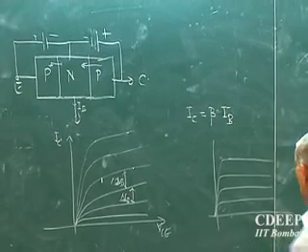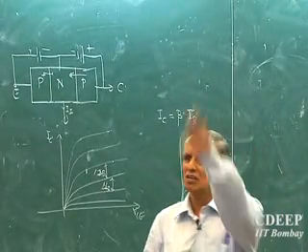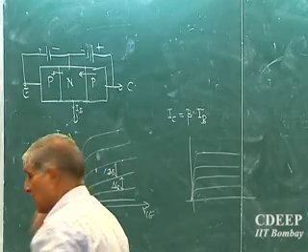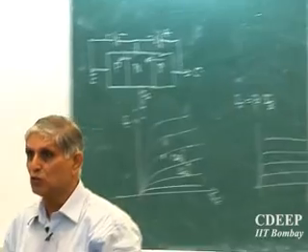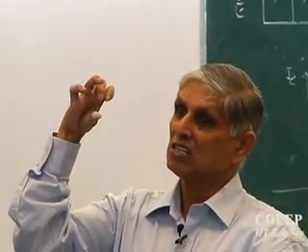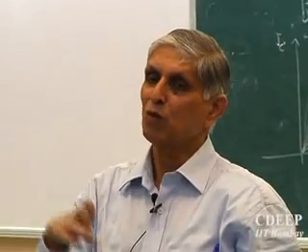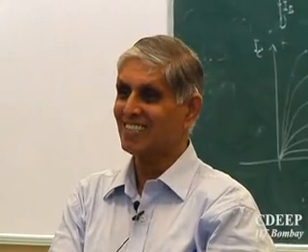Constant characteristics, so a change in IB should proportionally change IC by beta times that. But in reality, if I see a characteristic like this, for larger VCE values the change in IC is more than the change in IB. That means what has increased?